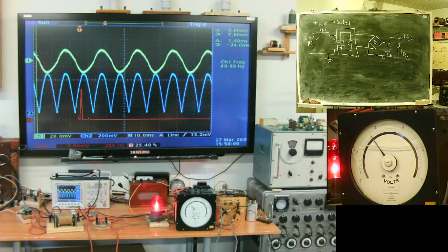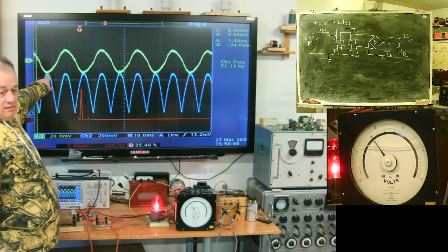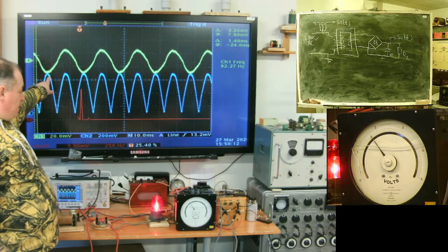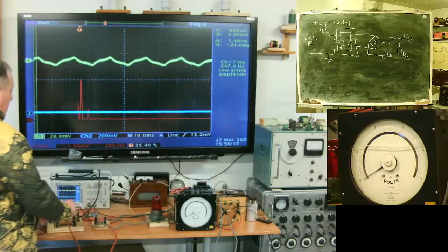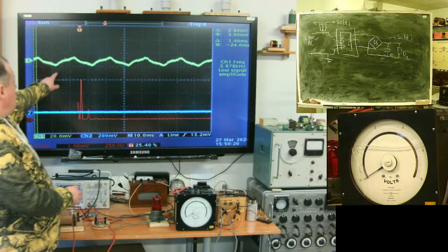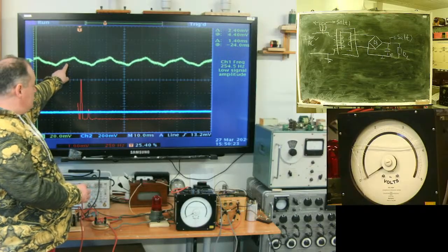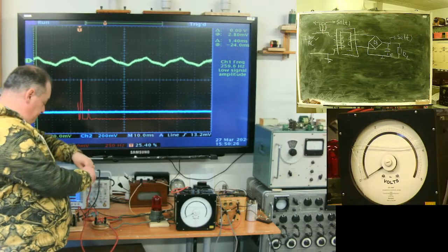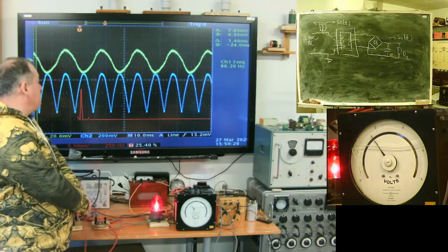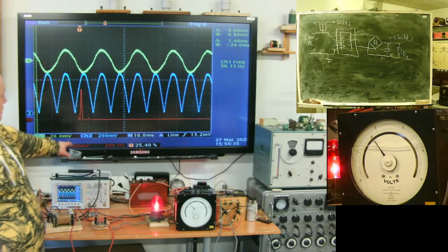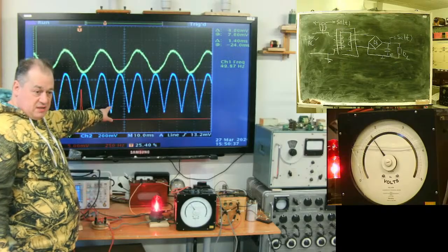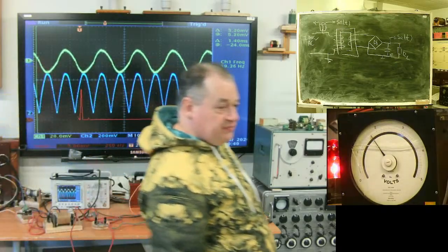Okay, now zero capacitance of the filter. Classical form from your book. Sine-like current on the primary side, a bit disturbed. Here I unplugged the load. We see some third harmonic, it's the magnetizing current of my transformer. Connect it again, here, a nice sine current at input, okay. And the classical two waves at the output of the rectifier.